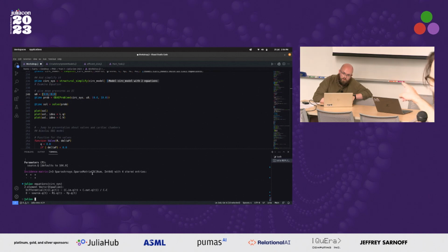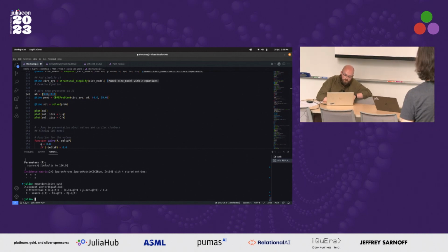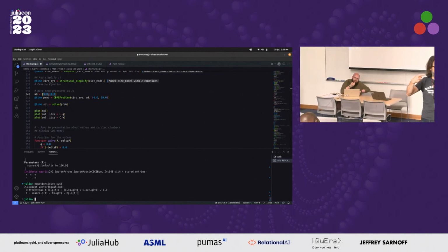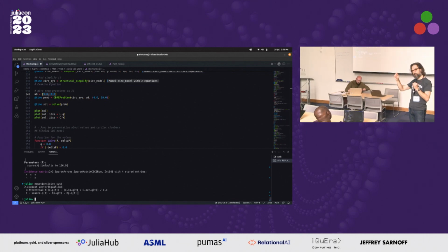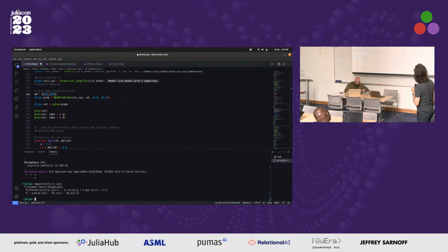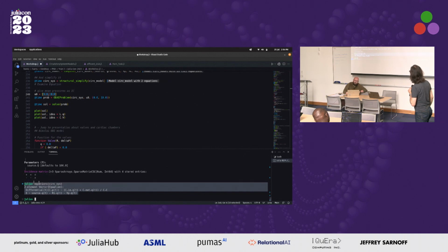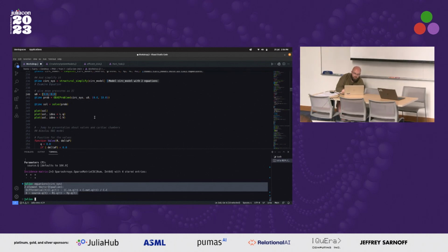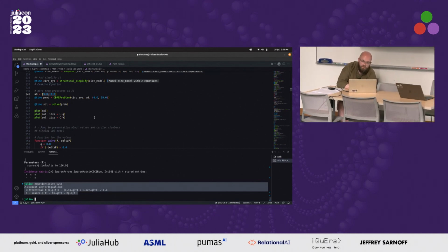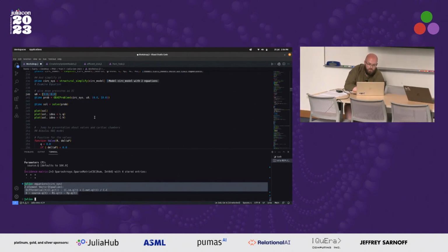That's why Harry, every time he does a structural simplify, calls the equations function, because the equations and then your system, which would be equations circ-sys, wouldn't it? Yeah. So this allows you to say, okay, that gives you the two equations, and that shows you in which order they are. In this case, we need one boundary condition for the pressure in the compliance. In the previous case, we had one boundary condition for the pressure in the compliance and one boundary condition for the flow through the system.